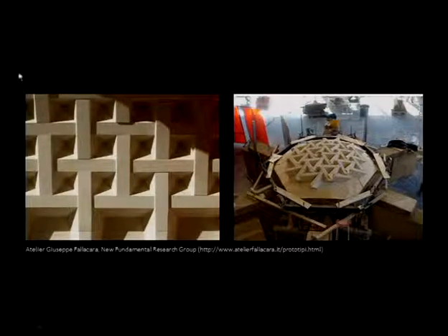But I'm just showing you these two examples of French vaulting systems. They're called Abeille vaults, A-B-E-I-L-L-E. And you see the cuts of these stones are already more complex. When you want to have almost a flat configuration like this, it's kind of easy. But when you want to have a triangular configuration, doubly curved like that, it becomes more complicated. So the way to cut these things is becoming more complicated.